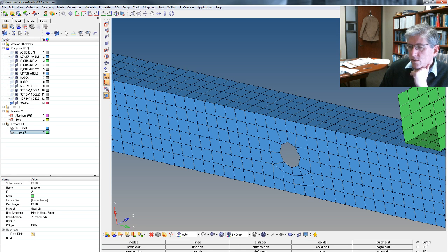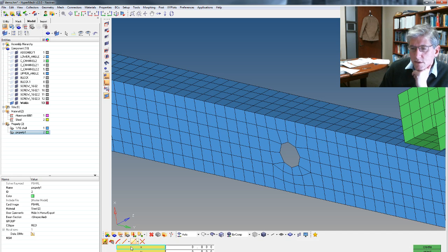So to generate nodes, we can go into geometry and there's a simple way to do this. If we click nodes, it gives us several options. But this one here with a circle arc and a node at the center is the easiest one. This will generate a center node, either with the geometry of a circle or by picking 3 nodes on the circle. So we'll select this to be nodes, and then we'll pick 3 points on the circle and do create, and there's our node.